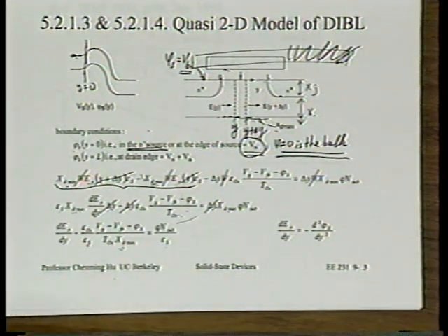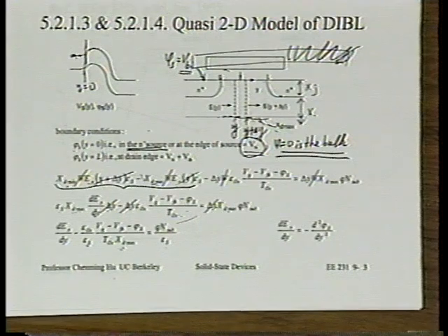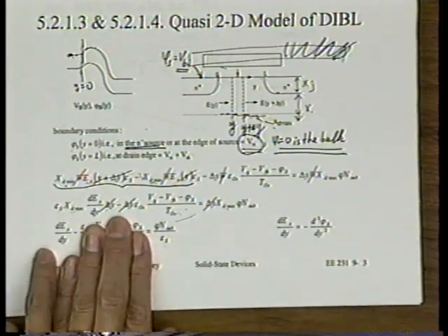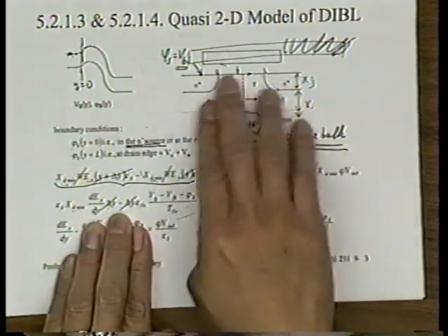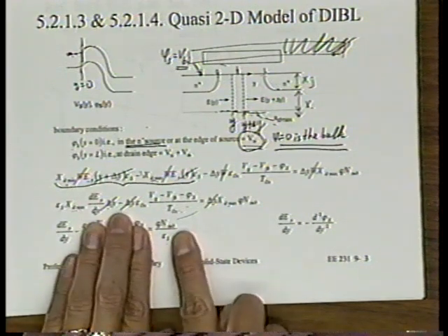What we have is really an equation very much like a Poisson's equation. It's dEy/dy. That's Poisson's equation. Is that right? And normally if you solve the Poisson's equation, you probably wouldn't have the second term. Just say dEy/dy. If this was homework, the first thing you do to solve this, you would probably say dEy/dy equal to the charge density rho.